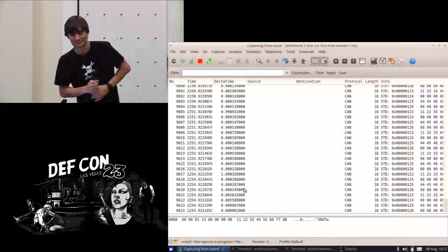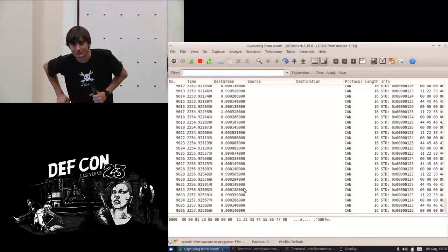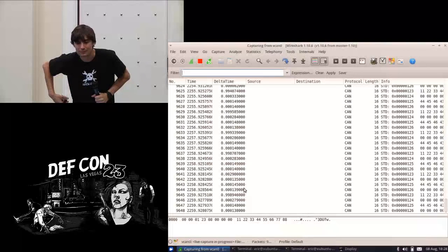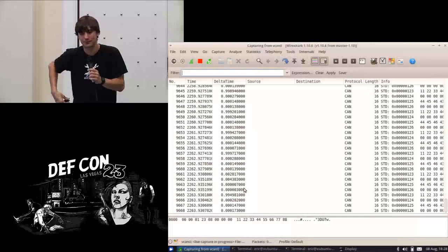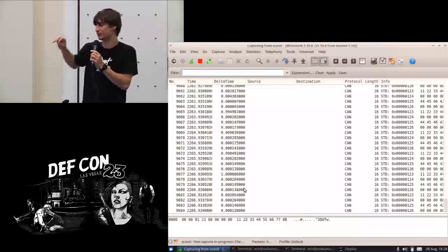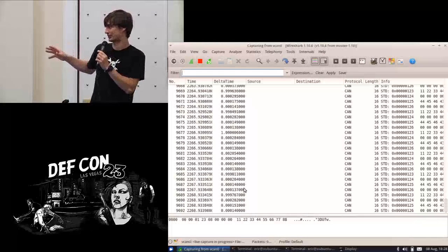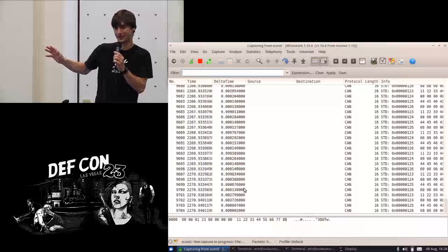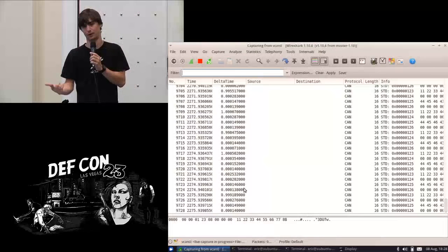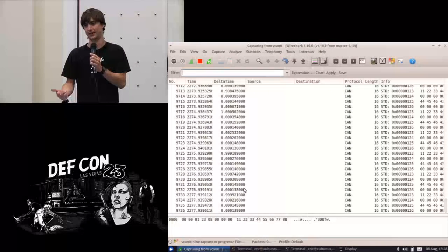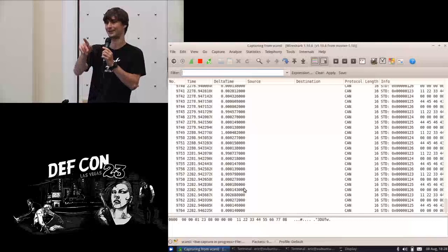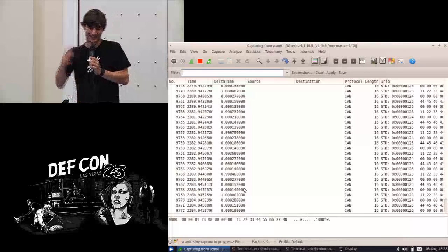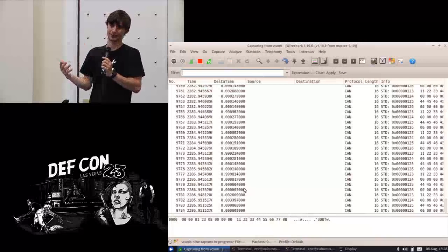Do these tools support the larger trucks? I think it's J1939 standards. I know they have different CAN messaging styles, formats. Sure. So this is raw CAN. This is just the messages. This will do anything except CAN FD. For those higher level protocols, J1939, OBD2, Unified Diagnostic Services, which is ISO 14229, I think. For those, you're going to need some higher level software.